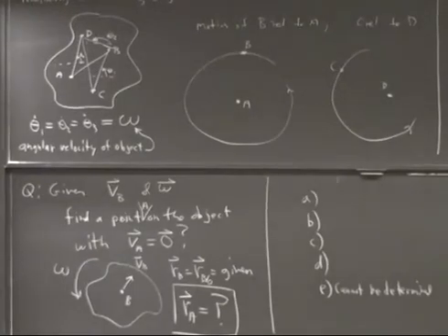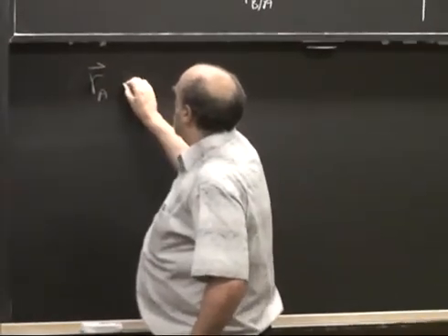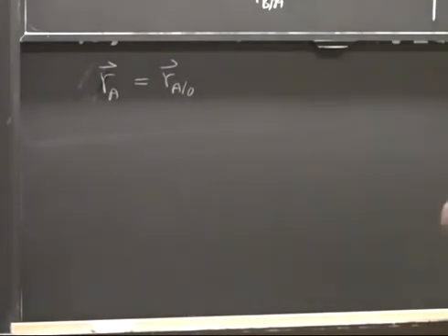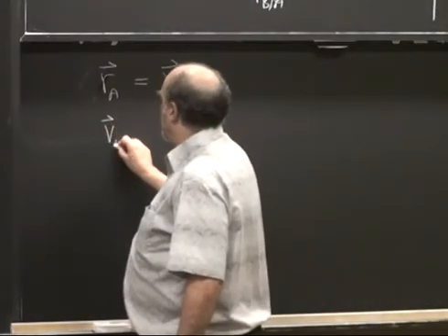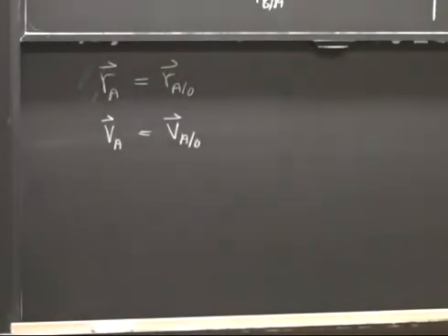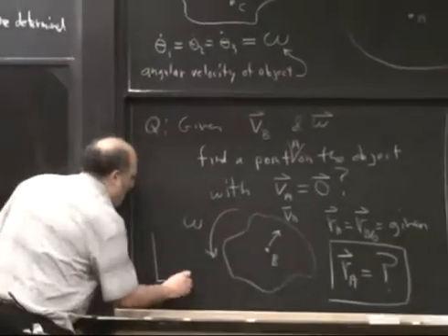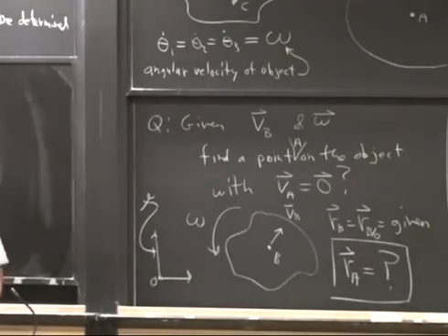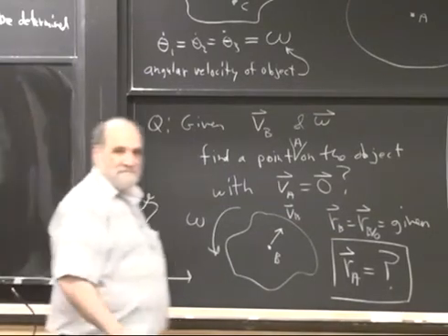What is it the velocity of A with respect to? So in this class, we've made a notational decision that if we write something like RA, what we mean by that is the position of A with respect to O. So if something doesn't have a fancy subscript, it always means with respect to some universally accepted reference point. So for example, if you write the velocity of A, it always means the velocity of A with respect to some point, and not just any old point, some point which is fixed in a fixed reference frame. So we always have in the background, for any problem like this, an assumed fixed reference frame, and in that fixed reference frame, there's some point O, which we're using to keep track of things. And we're using those coordinates to keep track of rotation. Does that address your question? That's always implicit.